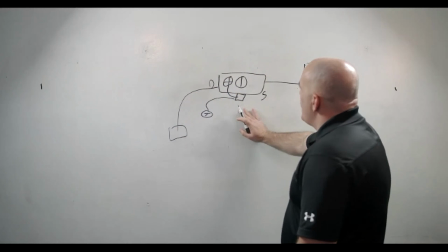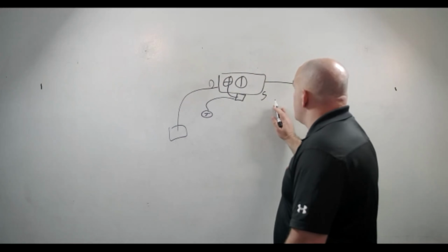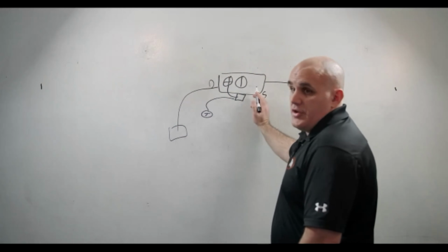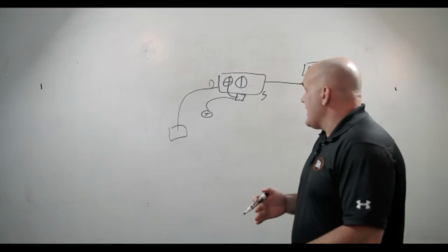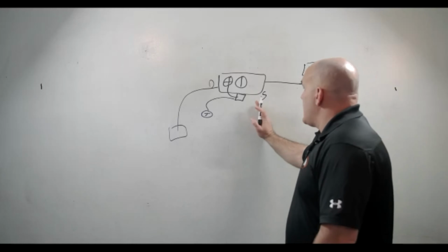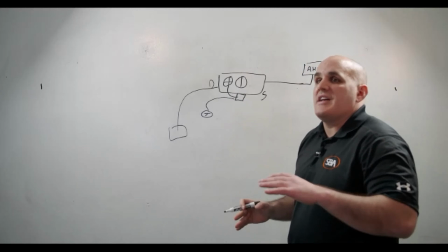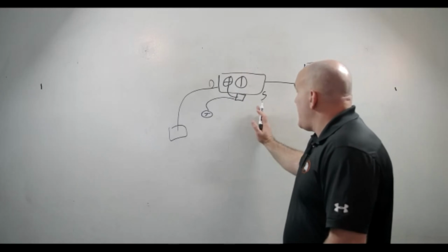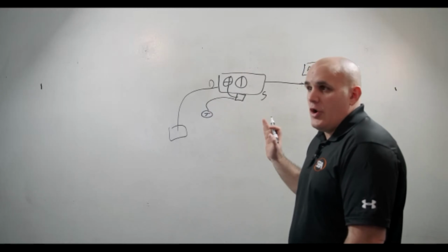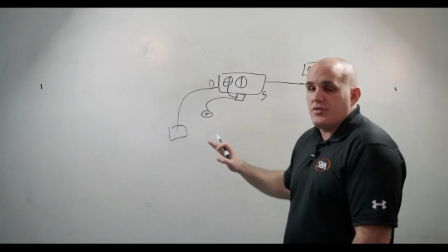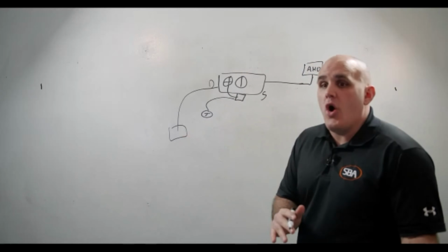Okay, so we've verified that our inputs work. We verified that it's only one terminal unit. Now we need to make sure we're getting air to the terminal unit. And if we are indeed getting air, then what's the next thing? Well, the next thing is going to be our damper. Are we actually able to modulate that air from the supply side to the discharge side? That's pretty simple. We just command it open, we validate that it opens, and we validate that airflow increases coming out. So once we've validated that airflow, we're almost there.